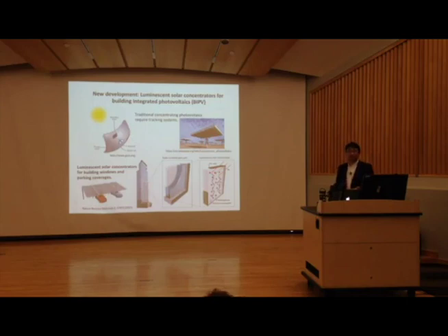Actually, it's not truly transparent. It really depends on what type of quantum dot you want to put in. As I said, if you can change the size of the quantum dot, you can make it different colors. You can make it red, blue, or yellow. If you make it red or even black, you can harvest all the sunlight and achieve the maximum efficiency. But sometimes it really depends on applications. For some applications, maybe people are not sensitive to the price. They care more about the color for decoration purposes. In that case, maybe they make it red or green colors.